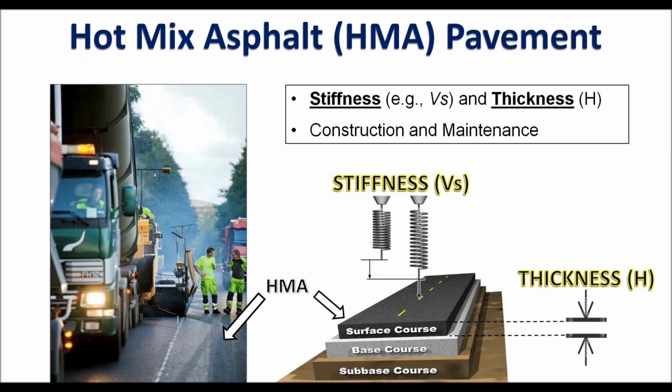So this project will be dealing with the hot mix asphalt, HMA pavement, more specifically in terms of evaluating its stiffness and thickness, both of which are very critical properties, not only during the construction, but also during the maintenance stages. And here I put this Vs, which is a seismic shear wave velocity, as a synonym to stiffness, and I will talk about why in a minute.